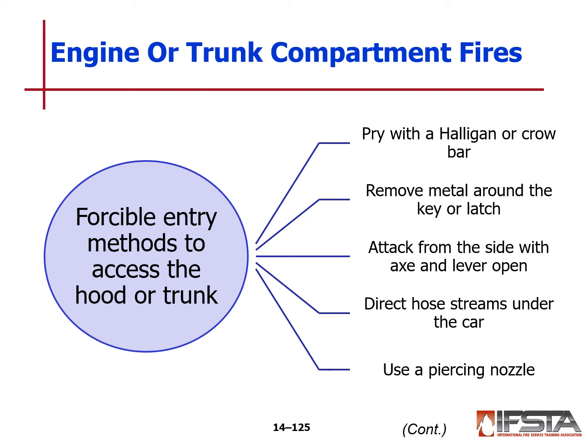Direct your hose streams under the car, and you may also even use a piercing nozzle, straight down through the hood. You can use a power saw to cut the latching device, cutting across the front of the hood. But again, be careful about putting yourself in front of the car, especially if the engine compartment is fully involved.